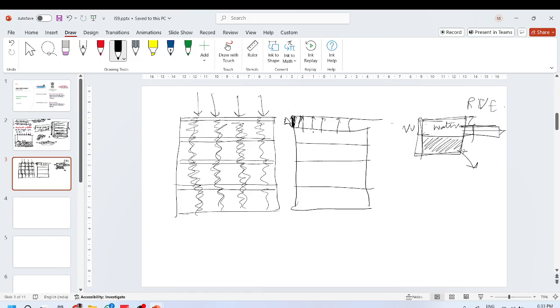And this movement of water depends on the permeability of the system. If the permeability is very low, then instantaneously if I load it, the pore water in this system will take all the load. And as the water moves out, you see displacement.